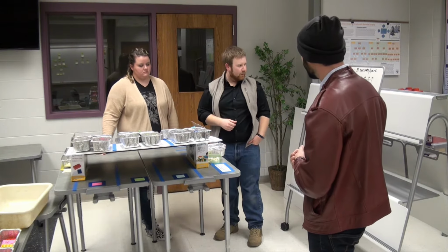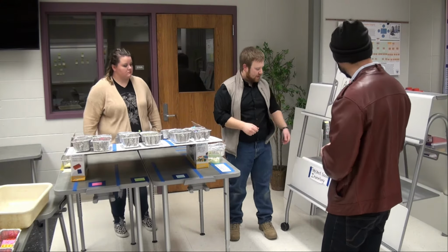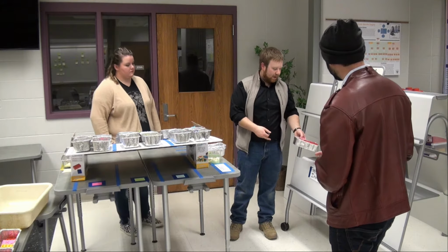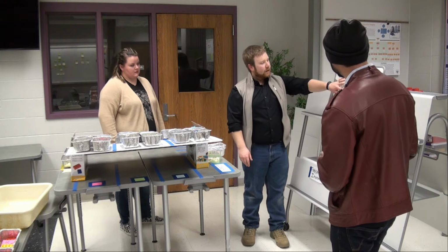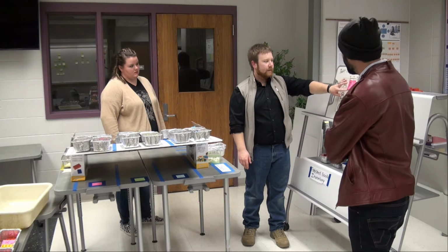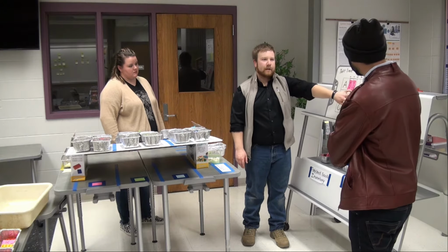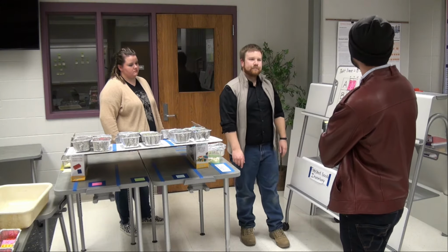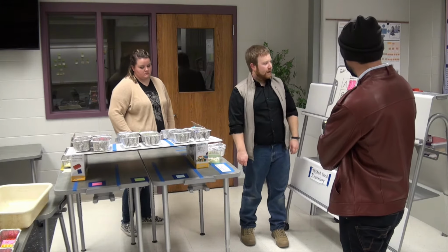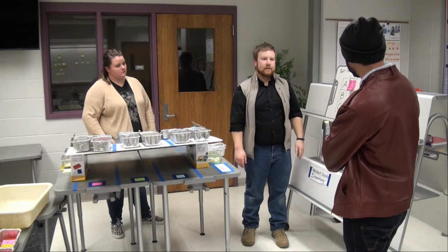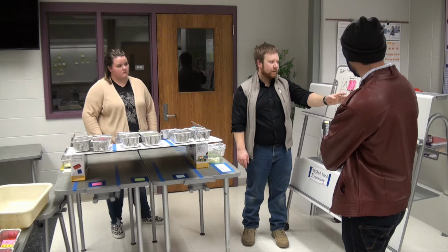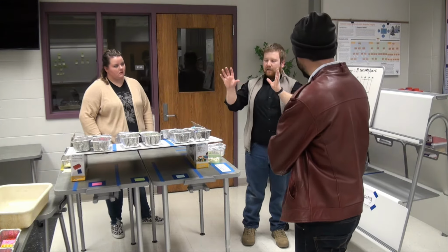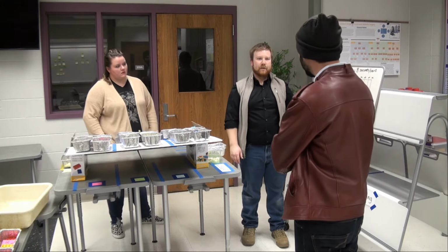Right. And so another thing that's a little different this time is the customer asks us to ship in containers of 4. So to run all the red first, we're going to pull a container of 4 red, and then a container of 4 red, 4 green, 4 green, 4 blue, 4 blue. Right. That gives us 8 of each color. Correct. And then later on, we're going to reduce the run size by staggering these. So red, green, blue, red, green, blue. So take 2 will show that, and it will show that the inventory is different when we reduce run size.